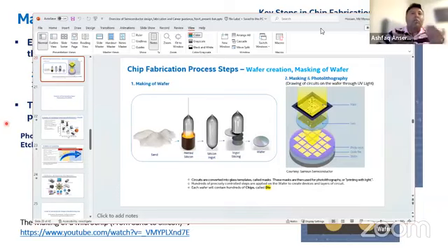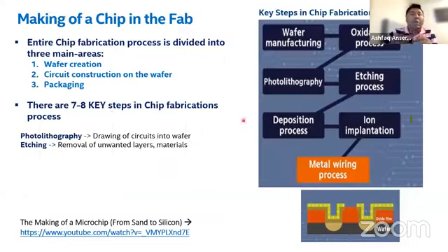And we actually remove all the unnecessary stuff from the wafer. When you use chemicals to remove these unnecessary materials, we call it wet etching. When you use gas, we call it dry etching. Now wet or dry etching is done, and we do the photolithography and etching process step by step, right?